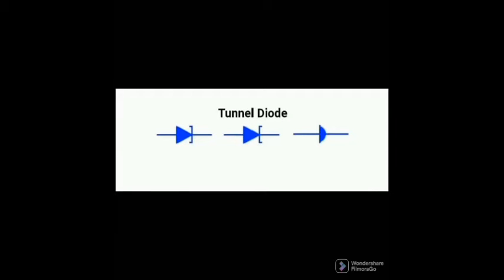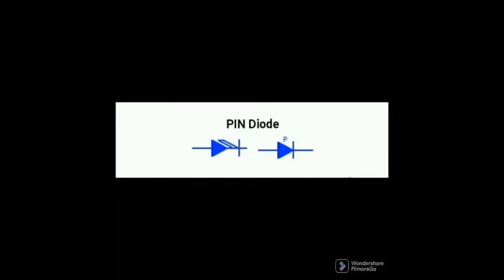This type of diode is made from heavily doped P and N semiconductor that works on the principle of the tunneling effect. Tunneling is the phenomenon of electrons escaping across the p-n junction due to heavy doping. A tunnel diode has a negative resistance region where the current decreases with increase in voltage, and they are operated in this region.